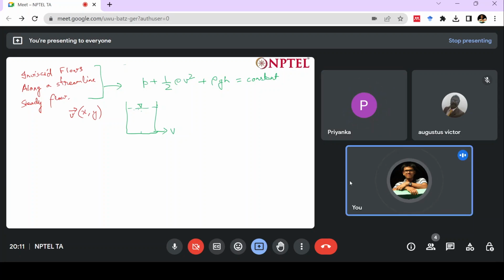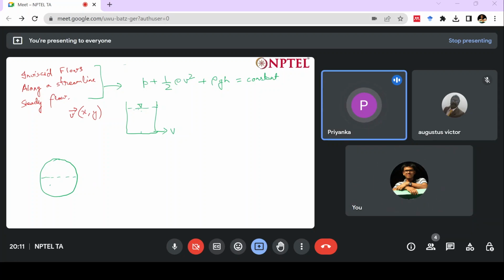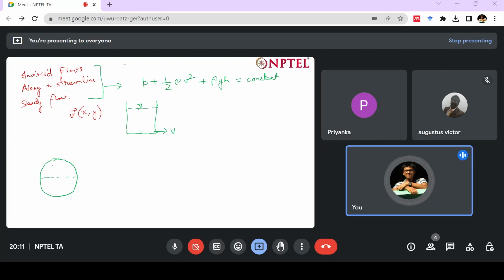Force on the bottom quarter surface. Let me understand your question first. You have a spherical container, right? And this spherical container is half filled with water. Then the other half is air with atmospheric pressure. Okay, so air inside here is at atmospheric pressure, there is definitely no variation with height here, at least for air. But for water, if it is working under gravity, you will still have this variation with height, right?